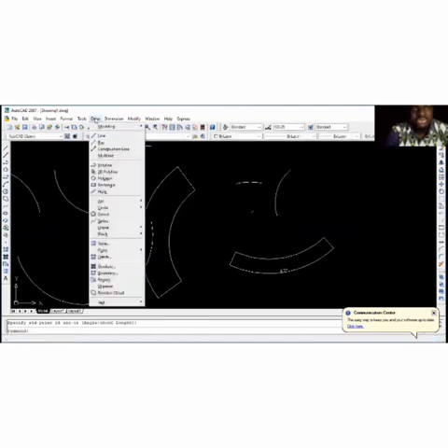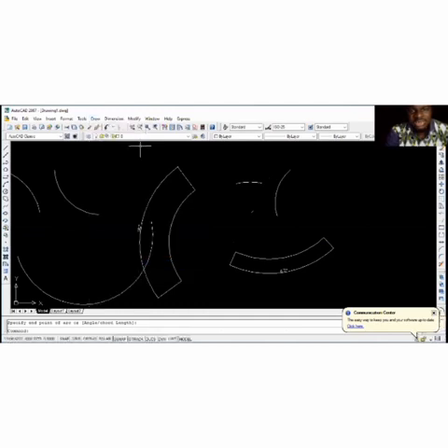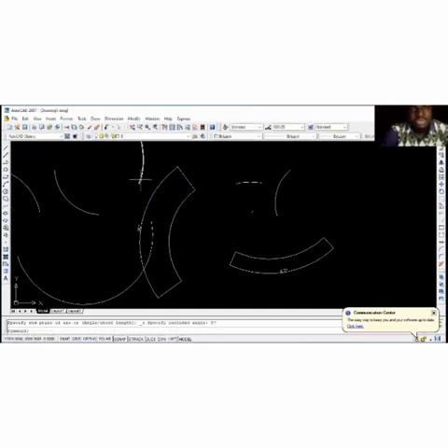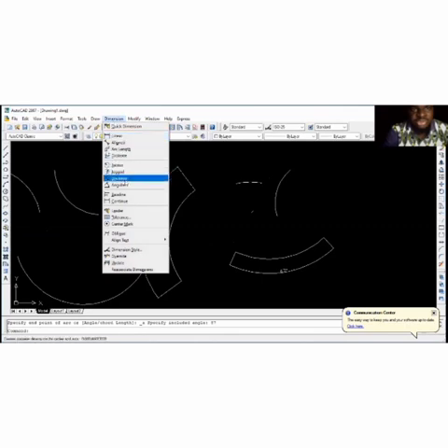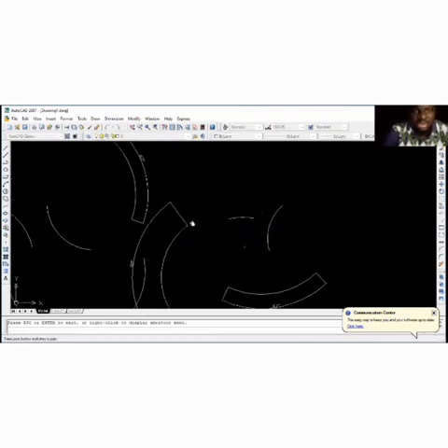So another option for your arc, we have the center, start, and then angle. So let's choose a center of this, the start, and then the angle. So we can choose another angle of 87, enter. So it means the angle of this arc is 87. We can measure it. Come to dimension, and then angular, you click on it, and that is it. So let's pan it, P, enter. So you can see it's 87 degrees.